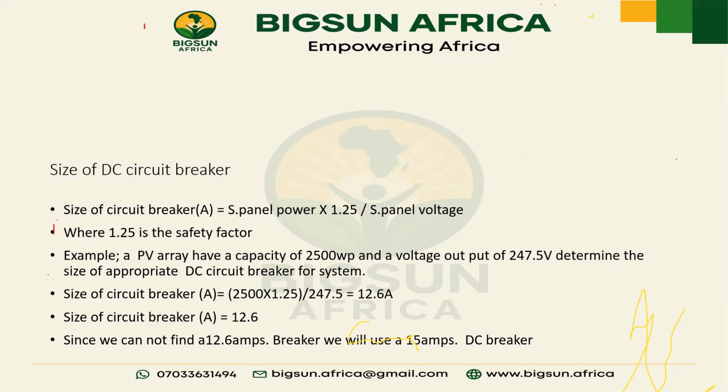For every design you are going to do, you have to know your panel VOC, VMP, ISC, and IMP. My question is, when you are doing this sizing at home, you've not seen the panel before. That's what I'm saying, that you have to know the panels that are available in the market while you are doing your design.